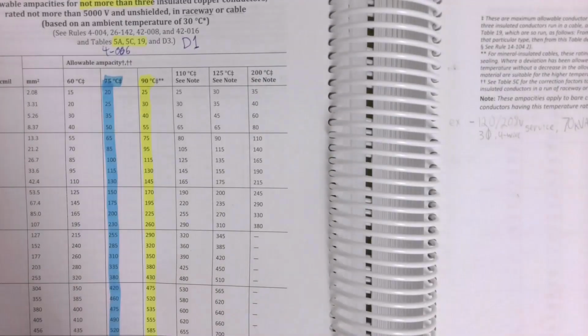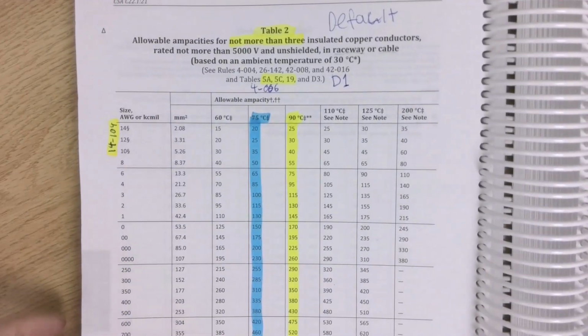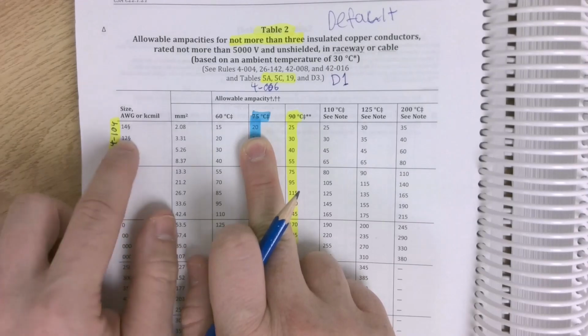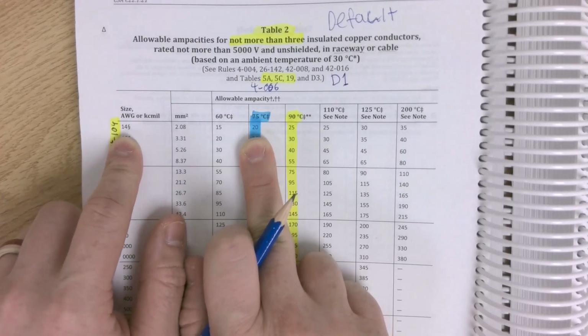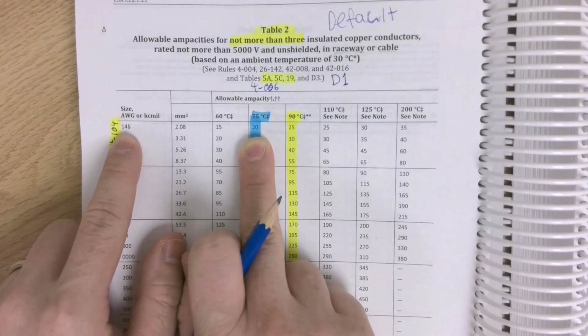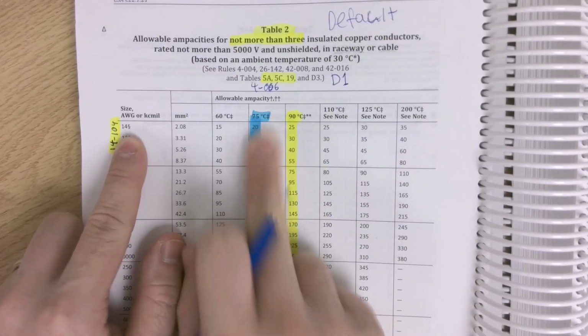I can't size my overcurrent yet because I don't know what wire size I'm using. So remember that the codebook says our default is copper. So I know that I'm going to use copper. I know that the question said all termination temperatures are 75 degrees Celsius. So I'm in the 75 degree column, and whoop, that didn't take long. The smallest wire, because it didn't say flexible cable or anything else, the smallest wire I can use here would be a 14 gauge. So perfect. And that's good for 20 amps at 75 degrees Celsius. Perfect.